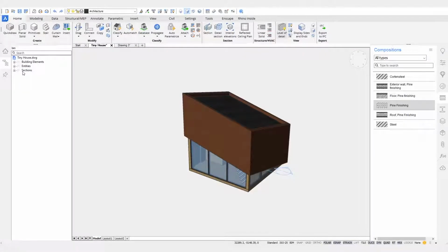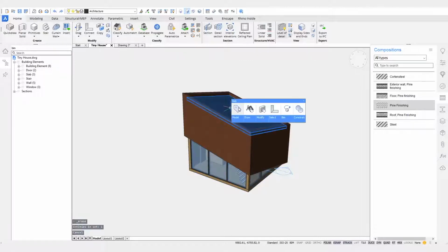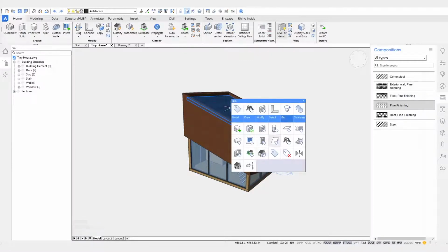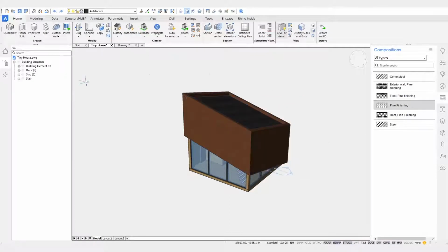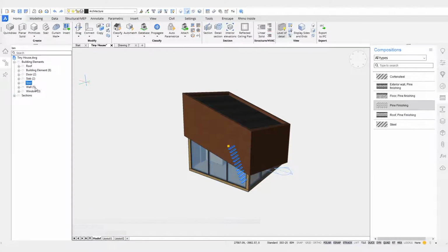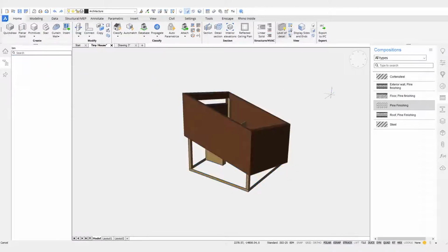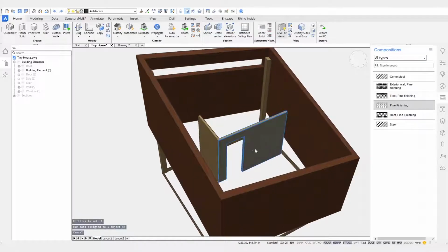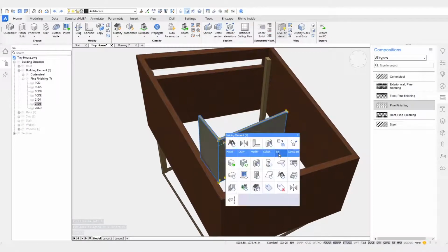I can use the structure browser for this. I can see here, in this case, I have 3 lines, which I will remove, and some building elements. So all of these things have already been classified. We have 3 windows, 7 walls, 1 staircase, 3 slabs, 2 doors, then 6 building elements. Building elements are basically the trash can of classifications. If you don't know what something is, just call it a building element and you're fine. But actually in this case I do know what they are. They're all coverings basically. So I'll just classify all of them.